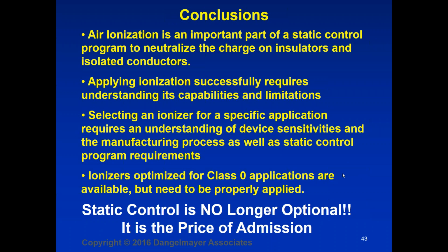And finally, the thing I'd like to leave you with is this last statement. Static control is no longer optional. The devices we're handling today are ESD sensitive, and they're going to become more ESD sensitive with time. The requirements we make on their performance guarantees this. So static control is not optional. It is the price of admission, that if you want to be working on electronic components in modern products, you need to make sure you do have a static control program.